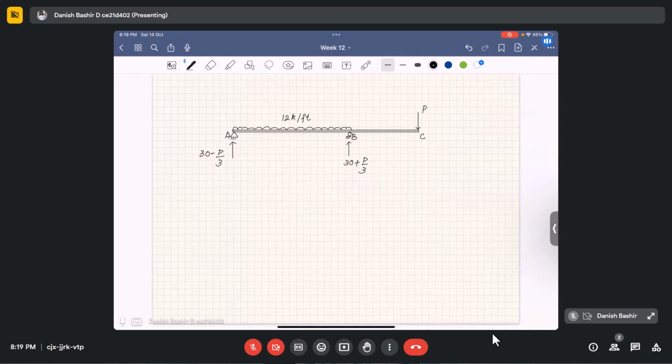Listen, we got it. Now, in the strain energy computation for problems and other virtual work problems, I told you to break your structure into different segments depending upon the loading condition and the boundary conditions. We do this for our convenience, so we can compute the strain energy very quickly by segmenting our structure. Here I am dividing my whole beam into two segments, using one coordinate system from here, x, up to this point.